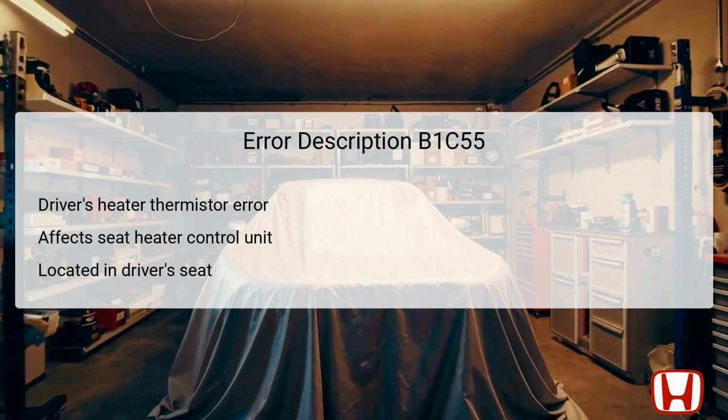The seat heater control unit is responsible for regulating the operation of the seat heater, which is further controlled by the thermistor's input. Located within the driver's seat, the thermistor senses the core temperature of the seat, indicating to the control unit when heating is necessary.